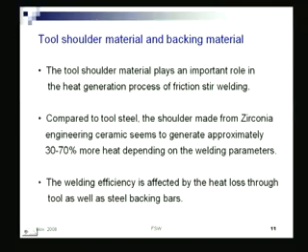Like in case of fusion welding, because of the arc heat, the immediate metal gets melted and that heat gets conducted and thereby further metal is melted and other aspects of deformation and stresses are formed. Here, because of the local friction, heat is generated locally and the heat gets conducted to further plastify the material. So, the entire heat is contained in the location where the tool is.